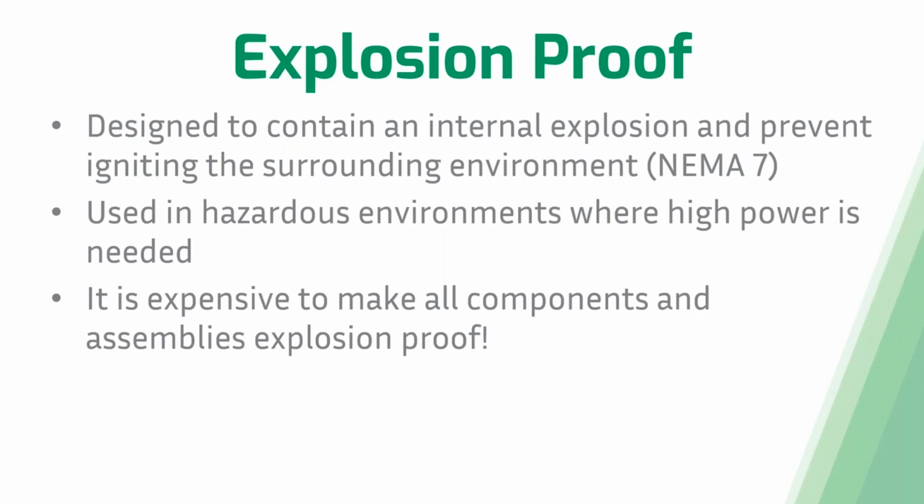Now, one thing to note is it is very expensive to make all components and assemblies explosion-proof, which is why you don't see a whole lot of explosion-proof panels. They do exist, but for most applications, you don't really need an explosion-proof panel. And because of that, it's going to be significantly more expensive than just an intrinsically safe panel. So that's just something to keep in mind.